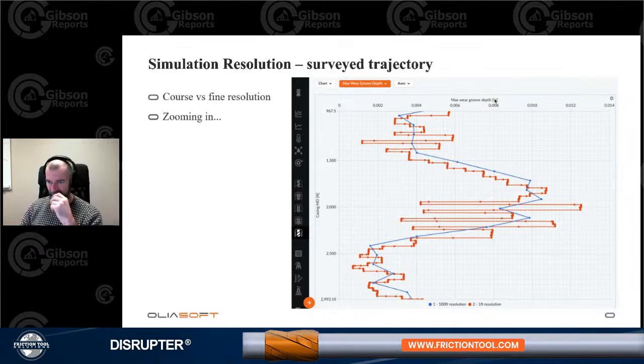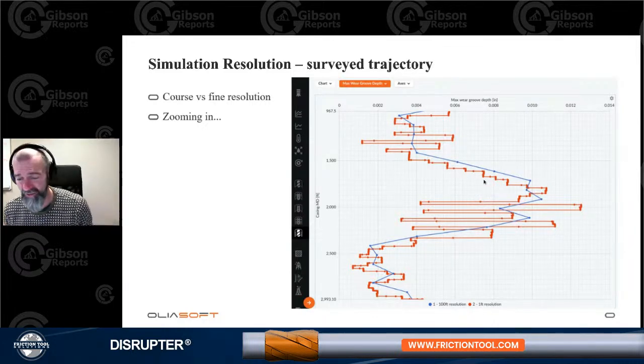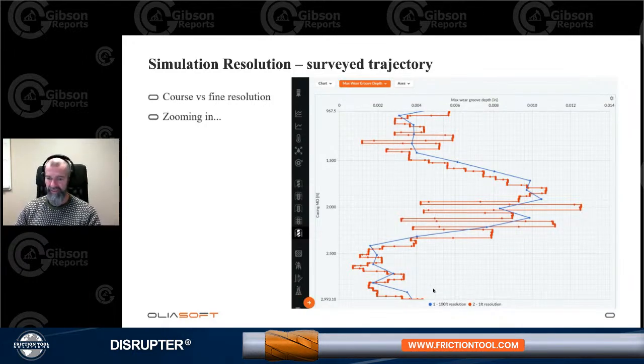Here I think I've run it with more proper parameters, and you can see that the small drilling operation and the reaming out actually doesn't cause much wear. We were at like 0.01 inch. So you need to do several operations to get wear that is significant. But what we're looking at here is the difference, right?